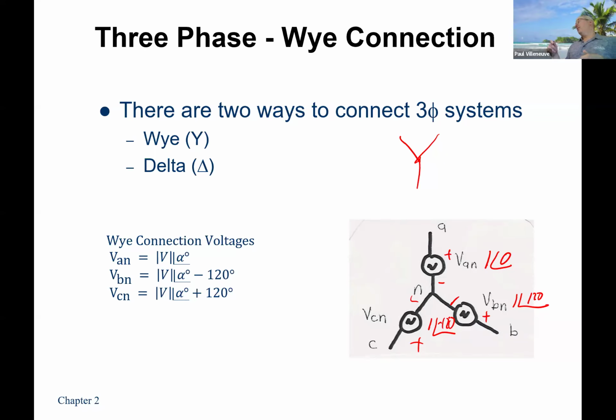A lot of times those pumps are not in the most populated area, so the utilities don't even run three-phase there. But you can take two-phase and run it through what's called a variable frequency drive. It converts the incoming AC to DC, and then you cut that DC up into three-phase, which is exactly what you did, and you get a three-phase power source. If you want to build one, you can buy a VFD from Automation Direct, and it'll take single phase in and give you three-phase out.